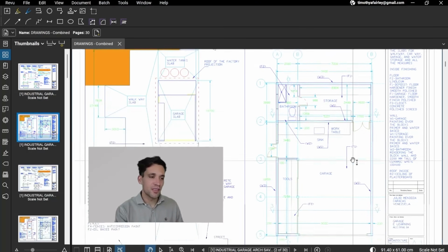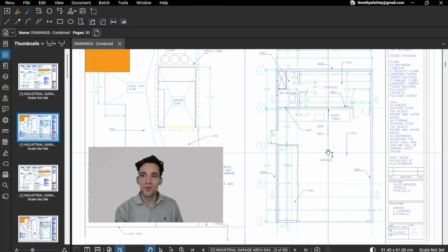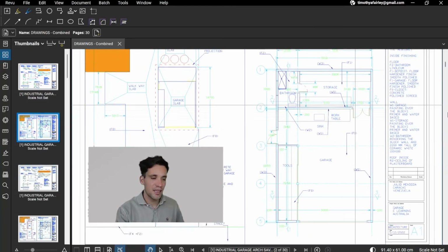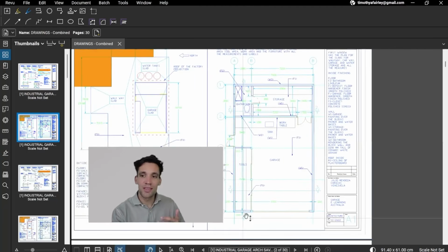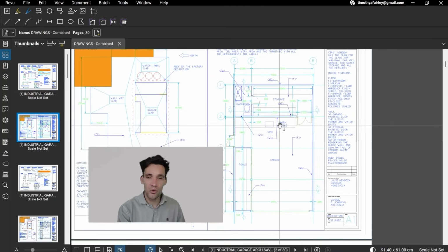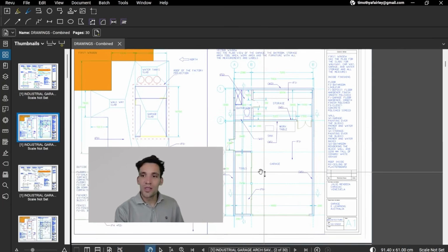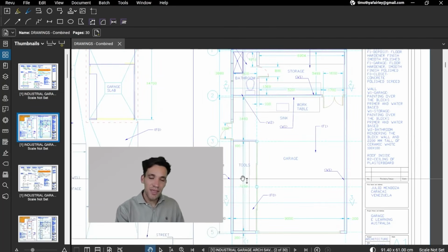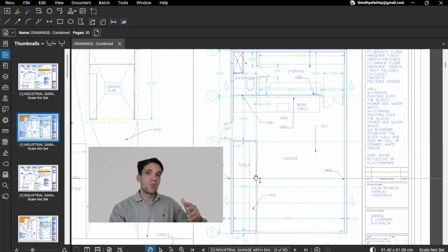The basic framework is really quite simple. You have a primary quantity that you measure from the drawings. For example, this will be the linear meters of wall that I get from the plan view. You'll then come up with an assembly that you apply to your primary quantity. So an assembly, if you don't know what it is, is a ratio of a primary quantity you measure to a full bill of materials or secondary quantities.